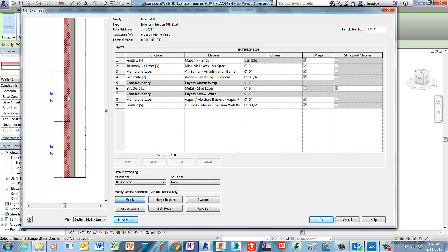Let's follow that up by merging the upper 2 wall segments back to a single wall segment. So click on Merge Region. And the trick here is to place your cursor over that horizontal line that currently separates them and left click to apply the merge operation. And now it's healed. And it's back to just one segment at that location.